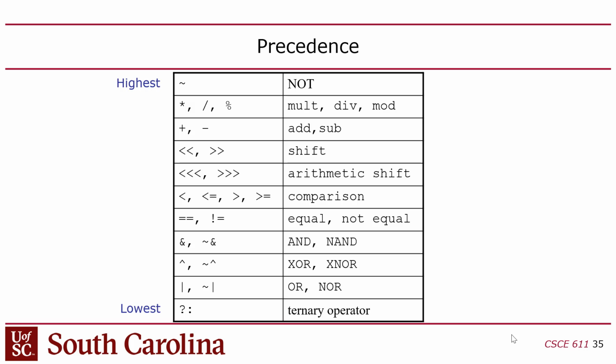Right? On the other hand, let me rephrase that. Actually, that's wrong. If you use equals equals and you put Z's in there, you won't get false, you'll get an X. Sorry, it'll be undetermined. So in the simulator, if you say Z equals equals Z, or X equals equals X, either way, the answer will be X, meaning I can't compare these: garbage in, garbage out. You're putting floating signals in, there's an undetermined value out. But if you use equals equals equals, then it'll be true if you have two Z's. It'll act like a programming language would if you compare two equivalent values, right? You guys with me? So yeah, sorry, that's the difference.